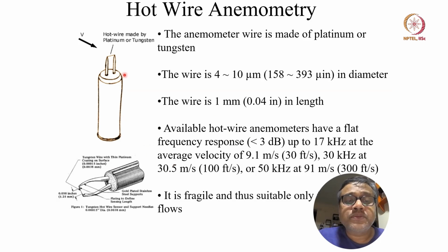It is fragile. That means if you touch this wire, it will break. Thus it is suitable for very clean flows. You cannot have a very dirty flow where there are a lot of particles or fragments which will hit the wire and break it.